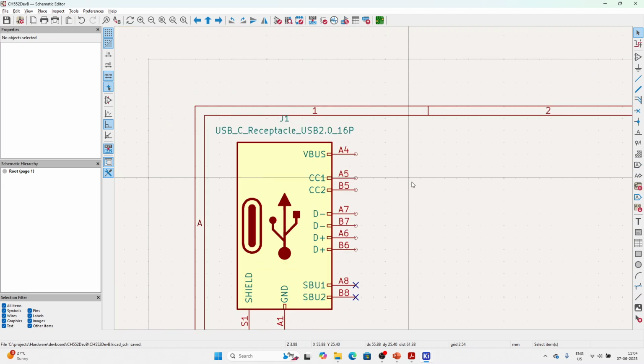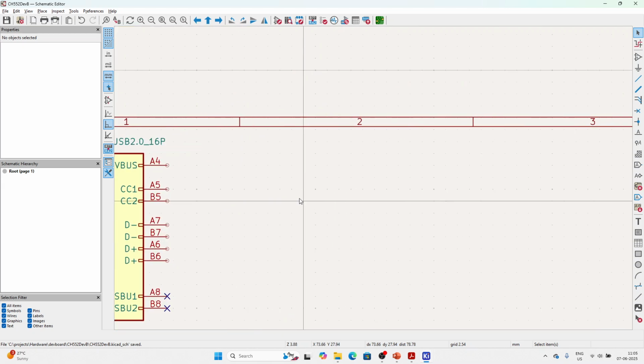So now there are multiple considerations with respect to power, because we have used USB-C. There can be two kinds of cables. One is a normal USB type A to type C cable, which would provide 5 volts at around 2 amps max, or USB-C to USB-C, where power negotiation might happen.